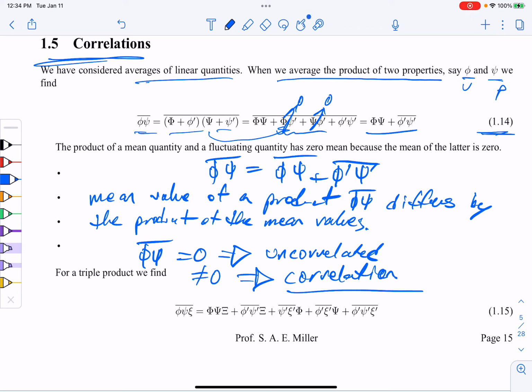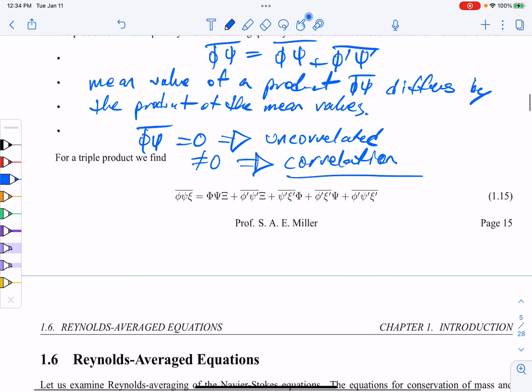So you can apply correlations, but it doesn't mean or apply cause and effect. And maybe it's good to give fluid dynamic examples because we're in an aerospace type class. And you might say, well, the stagnation pressure of the jet flow has increased as I increase nozzle pressure ratio. So there's a case where there's high correlation and causation. Or you might say the speed of the jet has changed because I've changed nozzle pressure ratio, and that is correlated, but it's not causation because that's also controlled by temperature. So there's examples where you have to be really careful. You might find high correlations, but it doesn't imply cause and effect. And you might see that a lot in our society.